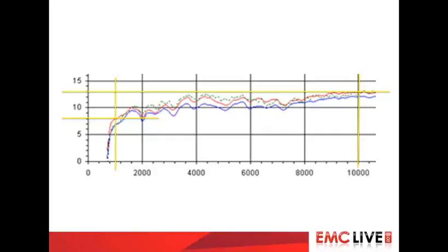Let me read those yellow lines for you. The first vertical yellow line you see reading left to right is marking 1 gigahertz. And that coincides with, let's count it for you, 5, 6, 7, 8 dBi. The antenna gives 8 dBi at 1 gigahertz. Then if we go to the right and look at the right vertical line that coincides with 10 gigahertz, then go left at the intersect and we read 10, 11, 12, 13 dB. 13 dB again.